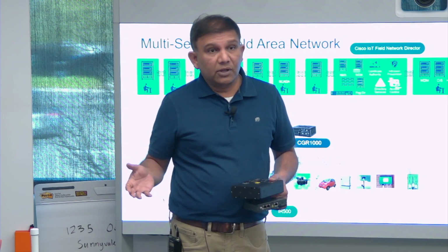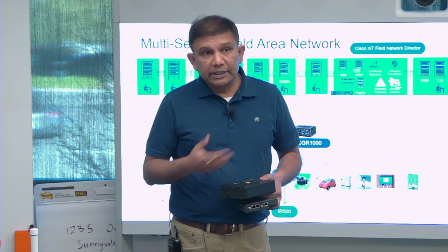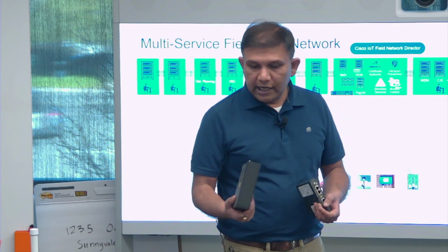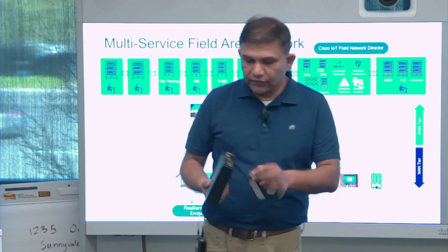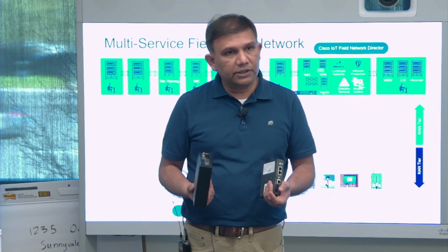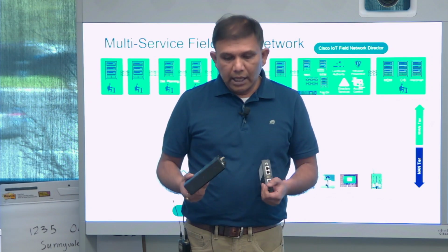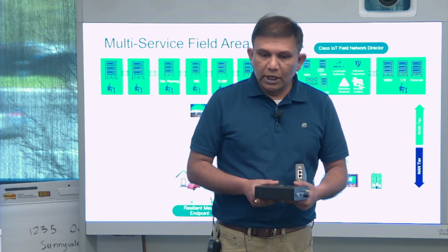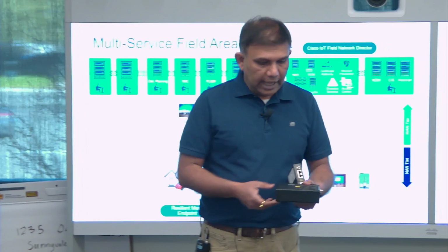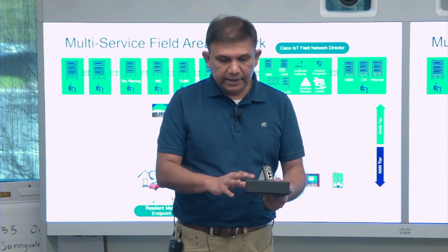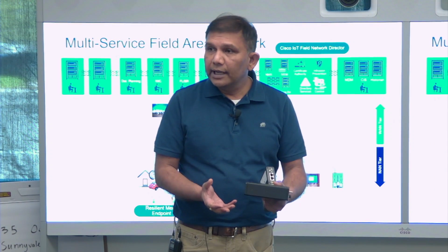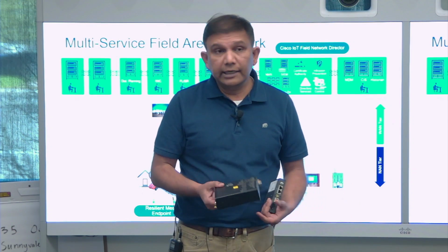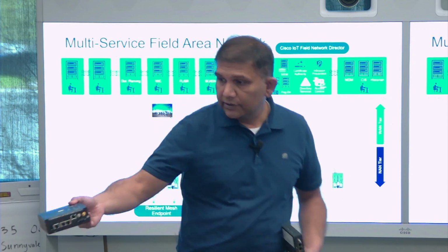They use SCADA protocols, DNP3 and Modbus, but they use it over serial, right? So a DA gateway essentially has, for instance, both of these have 2 serial ports and Ethernet as well. So you can connect the DA gateway to, like, a recloser control, and it has the mesh radio built into it, right? And so you can essentially enable that grid device with communications, right?